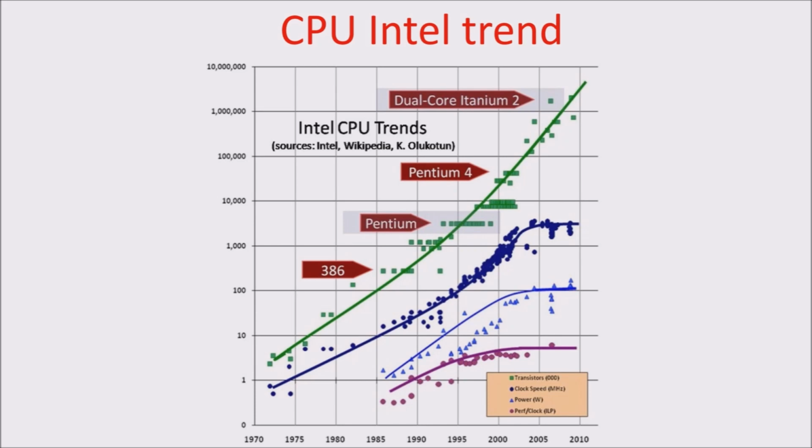The green line is the number of transistors inside the CPU, and you can see till 2010 it has increased a lot, and this means miniaturization. Intel always lowered the gate length until 2010 at a fast pace, but now the pace is slowing, and the 7 nanometers is planned for 2023. The blue line is the clock rate, and you see from the 70s to 2005 clock rate has improved by a factor of 5000, but after 2005 clock rate has not increased anymore.